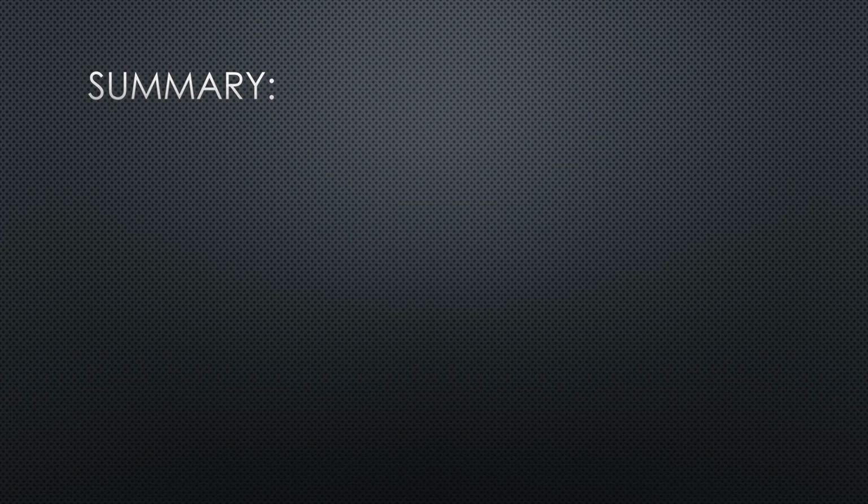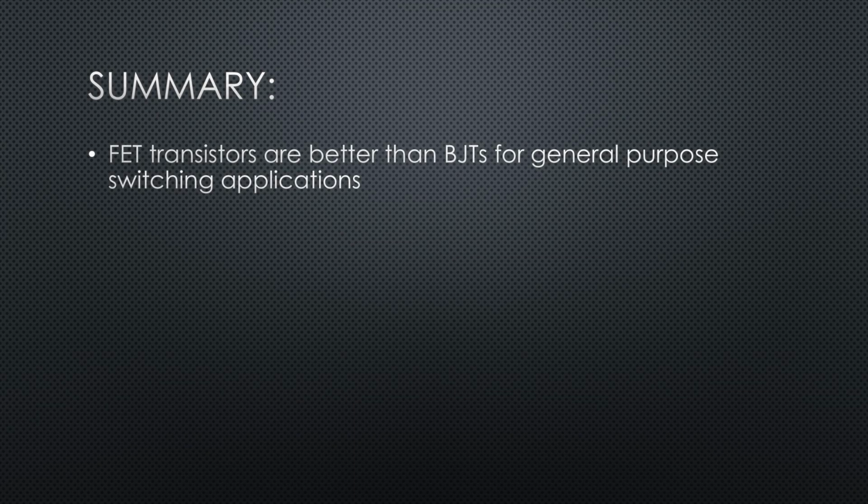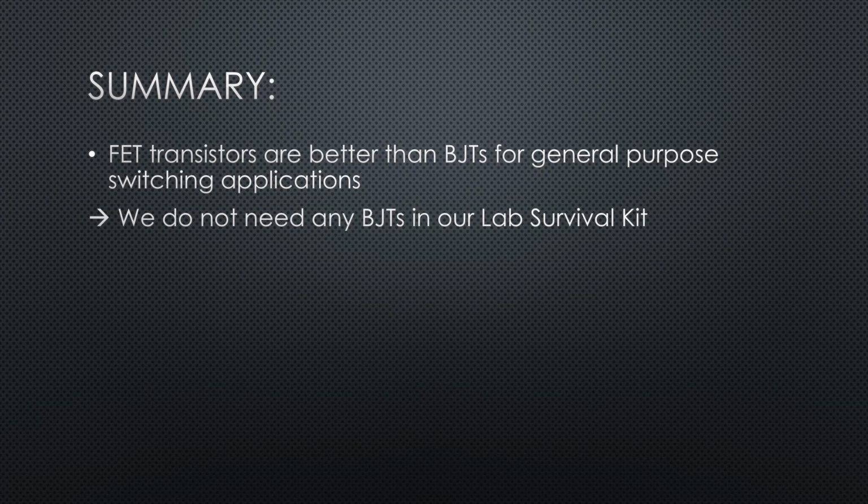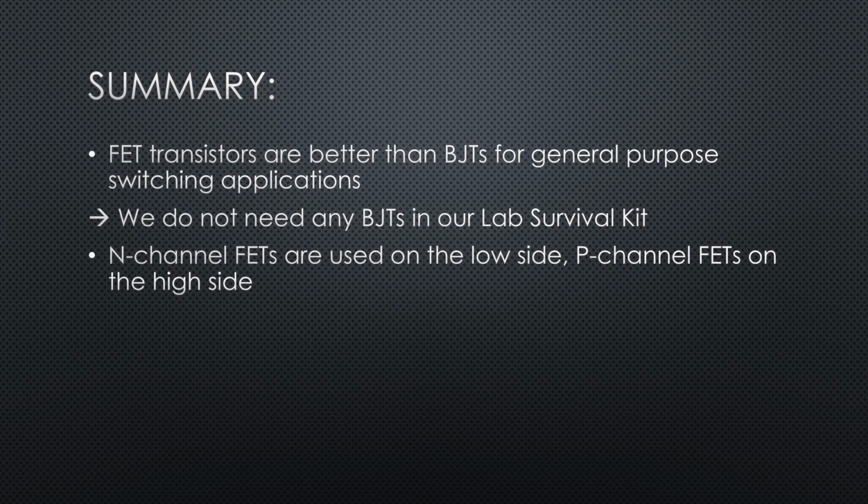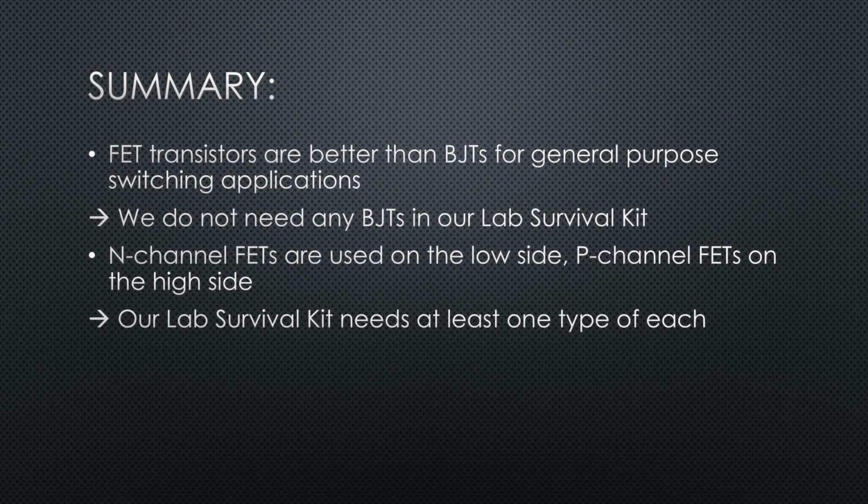So summarized, we learned that FET transistors are better than BJTs for general purpose switching applications. This is why we do not need any BJTs in our lab survival kit. N-channel FETs are used for the low side, P-channel FETs on the high side. This is why the bare minimum for our survival kit is 1 N-channel and 1 P-channel FET type.